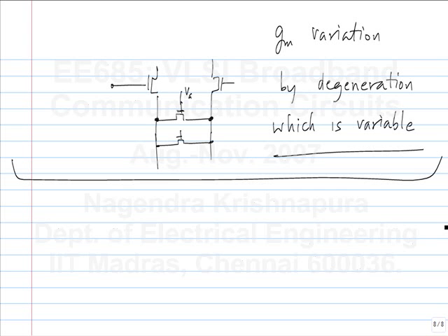Any questions on any of this? So there are a lot of details in implementation that you have to go through while making an adaptive equalizer. Even when making a receive equalizer, but particularly when you are making it adaptive, you have to make the coefficients variable. And you will always have to do more things like limiting the range and so on. For instance, one thing that could be risky is, let's say you make all the coefficients variable over a wide range. Somehow it gets stuck where the coefficient is 0 or very small. Then the output signal you get is also 0, and you can't do any more adaptation. Those kind of things you have to avoid.